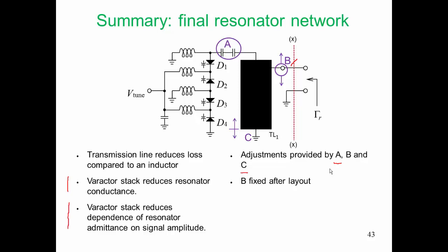So at the very final adjustment, a person working on the lab bench will have a shorting bar which they will have connected through kind of liquid solder. That shorting bar will be moved up and down to just get the finest of adjustments. Then the solder will be allowed to harden. In the next segment, we're going to talk about design of the active network.